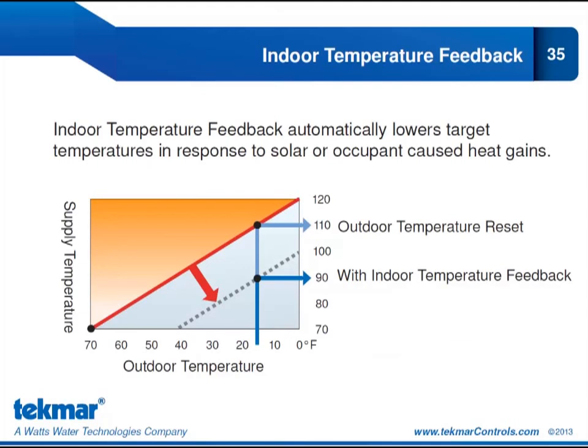I will also see fewer distribution losses, and I will have a more comfortable system that doesn't have the same temperature swings, those overshoots and undershoots that you see when we're working with supply temperatures that are higher than they need to be. I will also have less heat pump cycling, less expansion noises, so there are a lot of benefits to be had when you operate with the lowest supply water temperatures possible. And of course the biggest one is that added heat pump efficiency in the case of a geothermal system design.